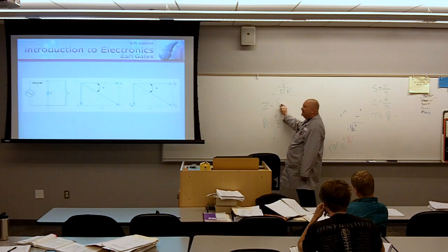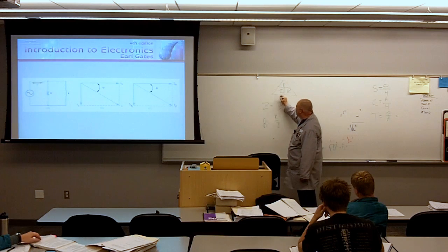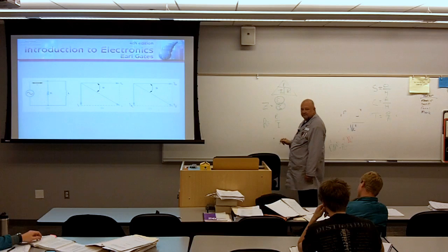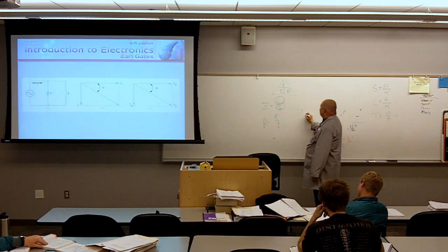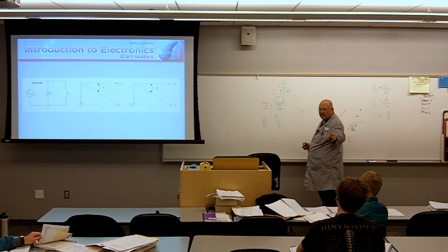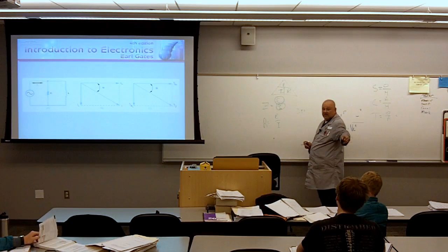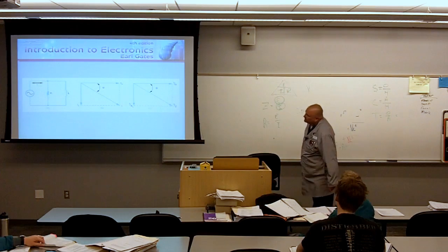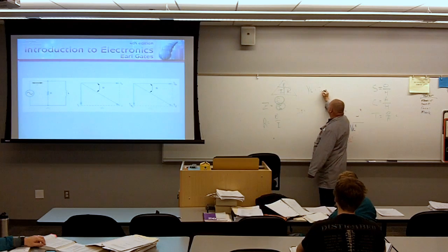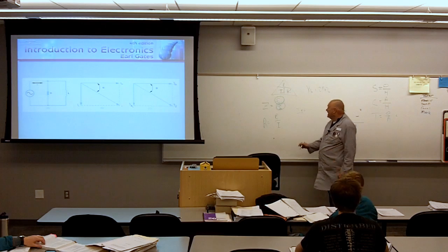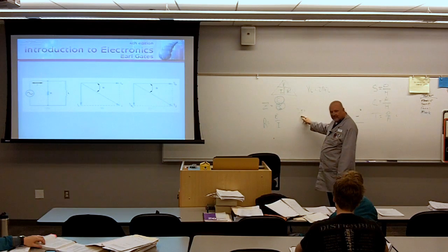The good news is this should be an easy one to get because it's the same voltage across the parallel network. This is kind of engraved in stone in a parallel circuit. How am I going to get this number? You have to find reactance. No, you don't have to find out reactance. That's the whole thing. I don't recommend you do that. If this has an inductor in it, X sub L equals 2 pi FL. You just calculated out your reactance. End of story.